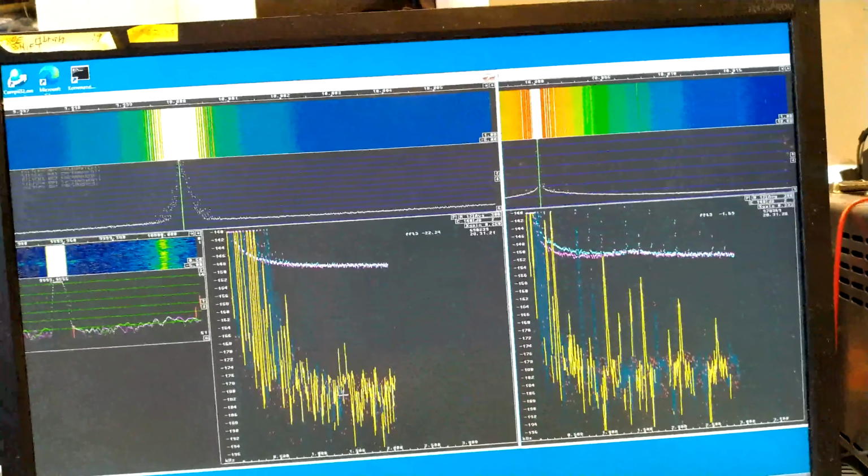The correlation gain from here all the way down here is rather big, and there could be problems with the setup. And that is clear here. You see these blue regions. That means that the signal is in antiphase, which is not the noise of the oscillator. And I don't know what it is. Maybe it's the spurs in the SDR-IP units.